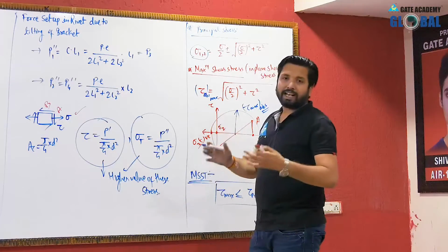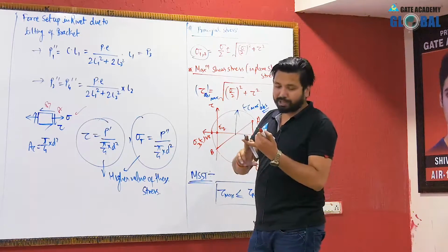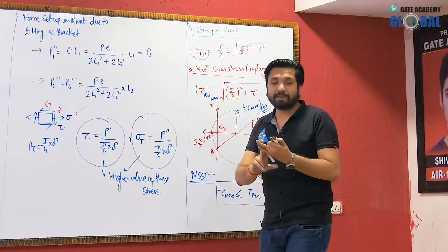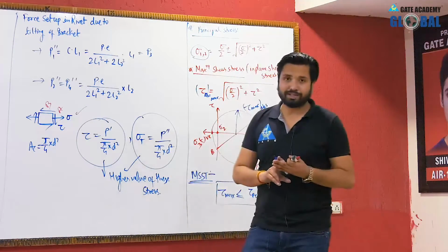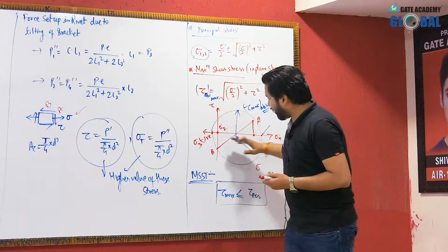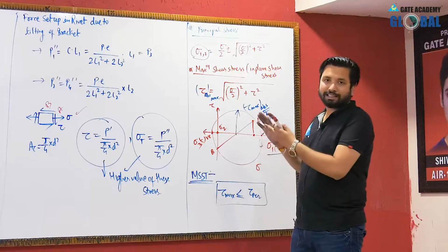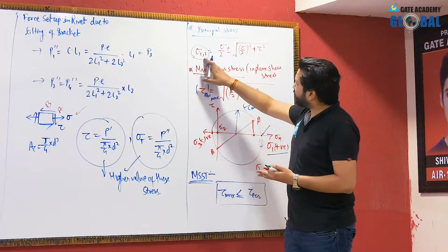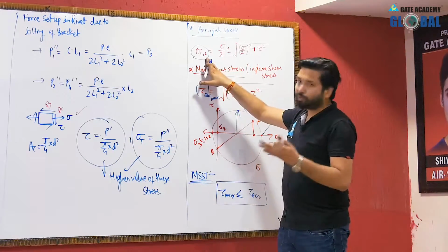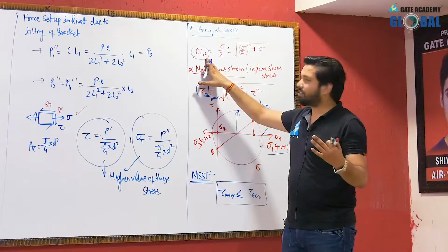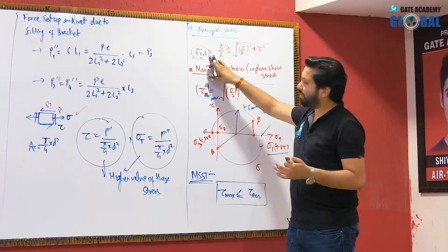Okay, and as per our consideration, sigma 1 is the algebraically maximum principal stress, sigma 2 is the intermediate principal stress, and sigma 3 is the algebraically lowest, or minimum, principal stress. So I have mentioned everything in the Mohr circle according to the algebraic maximum or minimum. Okay, but from here also you will get the maximum and the minimum value. So if you want to avoid any complications, then you can say that sigma 1 obtained from this equation will be the highest value and this will be the lowest value.